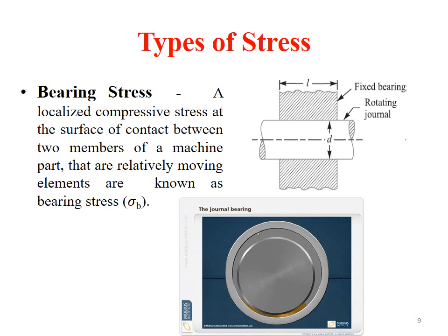Let us see bearing stress. A compressive stress at the contact surface between two members that are relatively at rest is called bearing stress, as shown in the figure and animation. Journal exerts a bearing pressure on curved surface. For example, journal bearings, pins used in levers are subjected to bearing stress.